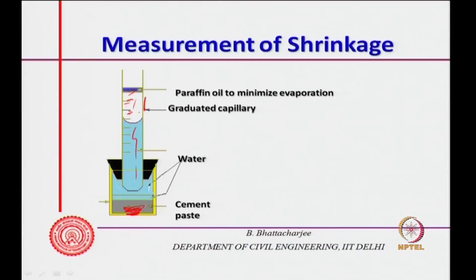So, chemical shrinkage is because of the volume change of this one. As the volume of this shrinks, the water level changes; full water is there, there is no evaporation loss, no drying, nothing is occurring. So, as we discussed, stoichiometrically you can find out how much volume change of the product would occur. So, you can measure this chemical change. This is done in the early stage.